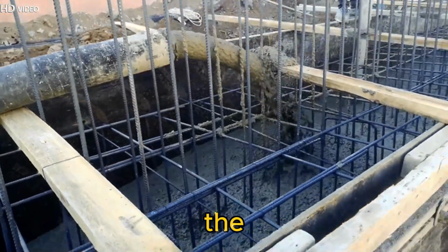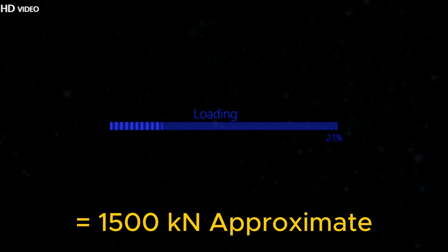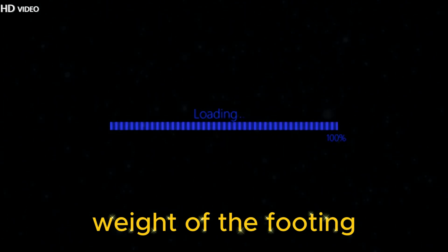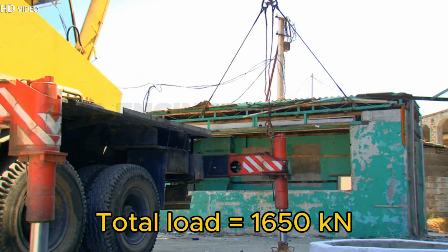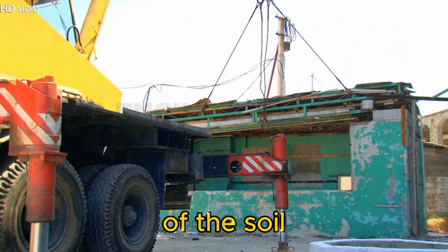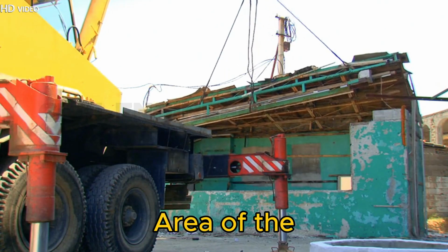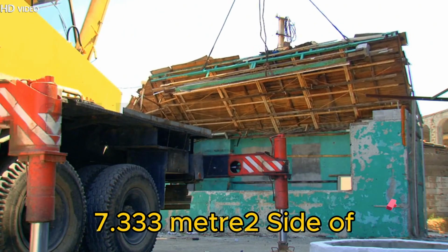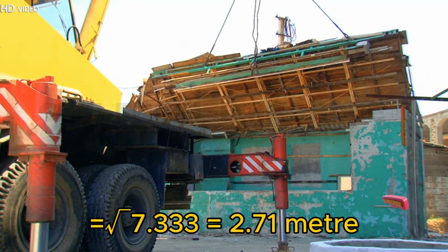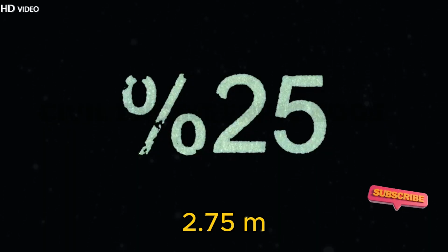Section 3. Design of the foundation. Load on the column equals 1,500 kilonewtons. Approximate weight of the footing at 10% of column load equals 150 kilonewtons. Total load equals 1,650 kilonewtons. Safe bearing capacity of the soil equals 225 kilonewtons per square meter. Thus, the footing is 2.75 meters by 2.75 meters.